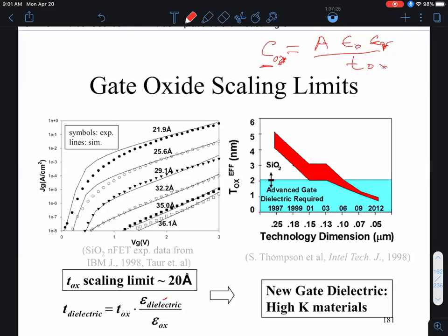Now, the challenge that people faced in this industry in the 1990s is the following. You want the gate capacitance, Cox, to be as large as possible. And for many decades, that was achieved by making the gate oxide, Tox, thinner and thinner and thinner, okay? But the oxide, which is of course an insulator, provides a barrier to current flow from the gate. If I plot the cross section over here for a second, that's my gate, that's my oxide, and then I have my source and drain. So we are looking at, of course, this capacitor structure.